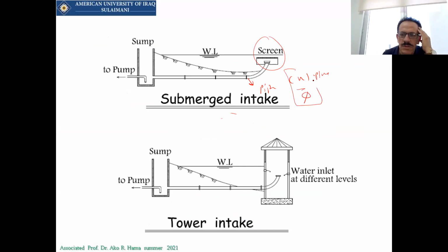So based on the velocities in these pipes, we have a V actual velocity, a V minimum, and a V maximum, or peak. The V actual will be equal to Q maximum monthly divided by N, divided by the area of each pipe.